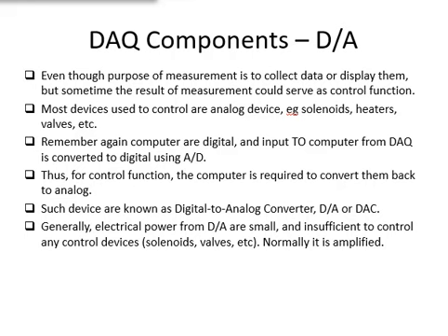Generally, the output electrical power of a DA converter is insufficient to directly operate most control devices such as a proportional valve. Consequently, the output of the converter will be used to operate an amplifier, which will in turn supply the power for the activated control device.